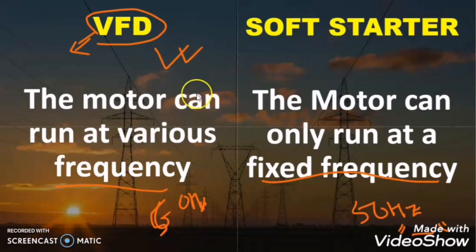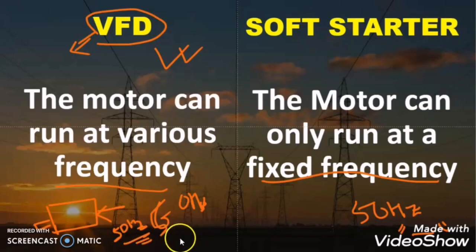Some VFDs also increase the frequency more than the power frequency, but that application is very limited and used in very precise areas. The reason is very simple: motors are designed with a rated speed, and that rated speed is determined using the power frequency, that is 50 Hz or in some countries 60 Hz. If you run the motor at a higher frequency, like 60 Hz, 70 Hz, 80 Hz, then the speed of the motor will become very high, which will cause mechanical wear and tear in the motor. So it is not recommended to operate the motor above its rated speed. Okay, hope you understood this one.